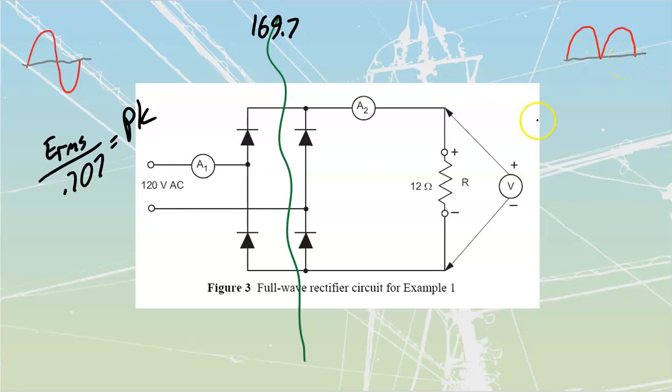So I'm going to have an RMS value of 120 volts RMS over here. If I have got 120 volts RMS on this side, I can figure out my power by using any one of my regular power formulas, because RMS is always used to develop power. Do I use my average to develop the power? Absolutely not. Could I? Yeah, I could do some conversions from average, take it to peak values, etc., and then get that down to a watts value, but why would I take myself through a bunch of steps that I could screw up when instead I could just jump straight into my RMS, the not-lying-to-me power thing?